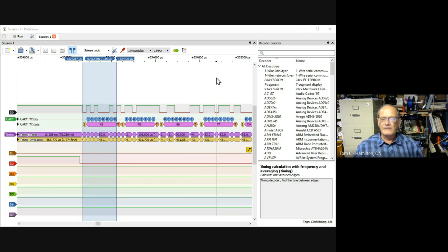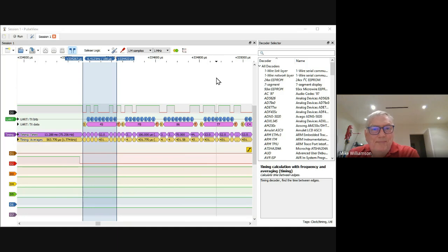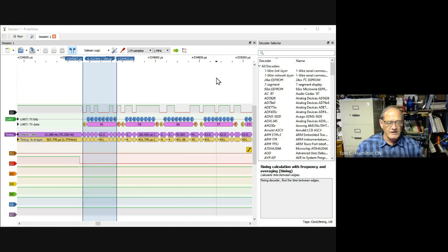Based on 1 day of intensive work, I've been at this most of today, troubleshooting the software design issues and a few other bits and pieces with my cobbled together encoder, without a logic analyzer I would not have solved these problems. It's that simple. Or I wouldn't have solved them today. I might have been working on them all week with a scope. But I'm working with a DigiSpark, and of course, the problem with a DigiSpark is you have no console. So it's like troubleshooting naked hardware.